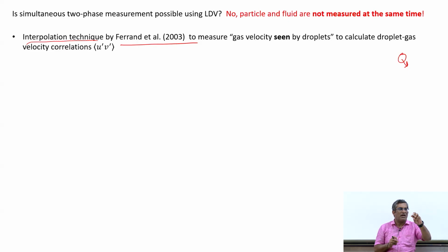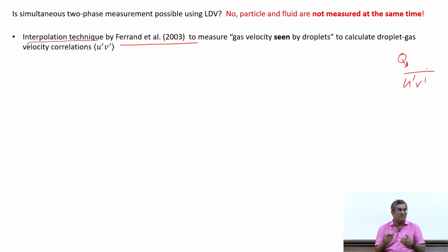For instance, you can model the drag force using the Stokes drag model with some correction factor, but you won't be able to calculate the boundary layer around the particle, because you are assuming that the particle is physically not present. This is what the point particle assumption is. So in the point particle assumption, these kinds of terms come into the model equations. We have discussed this earlier.